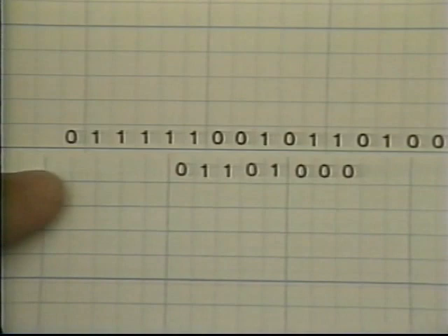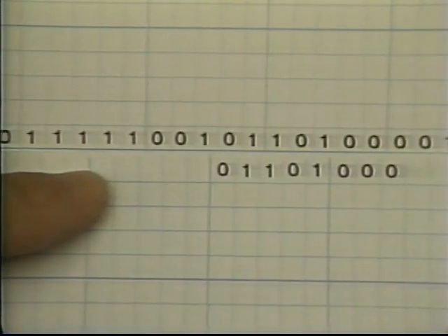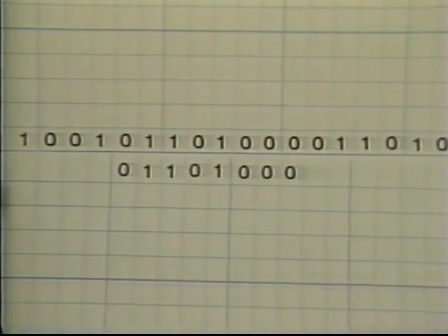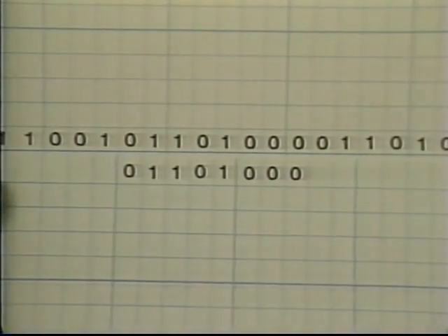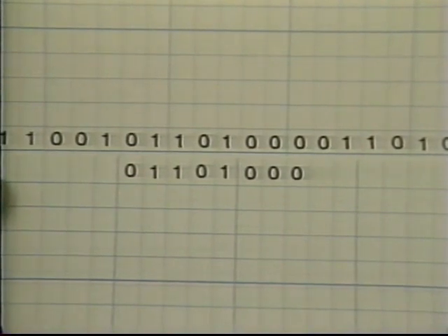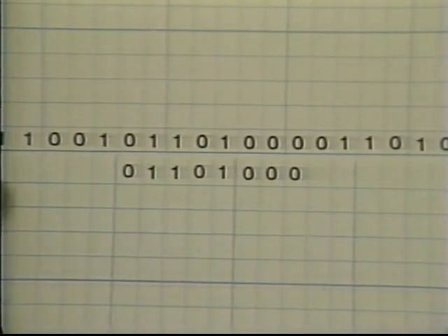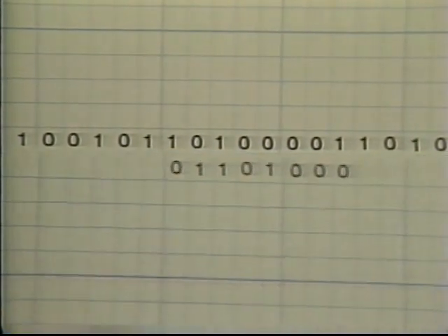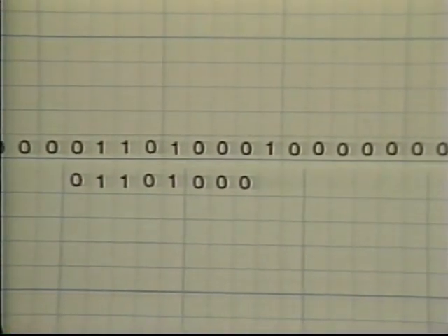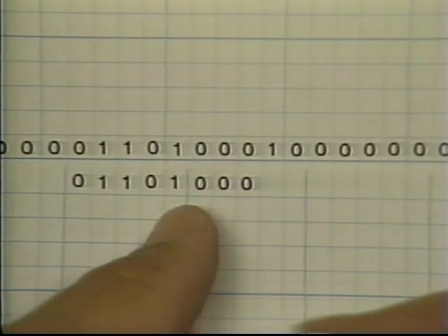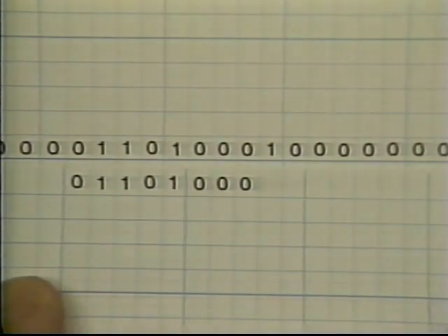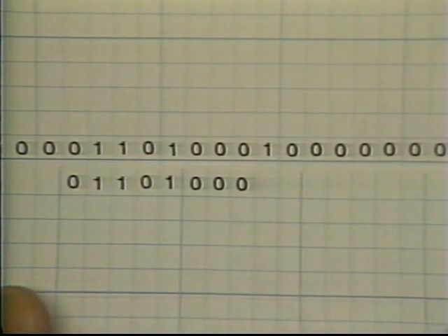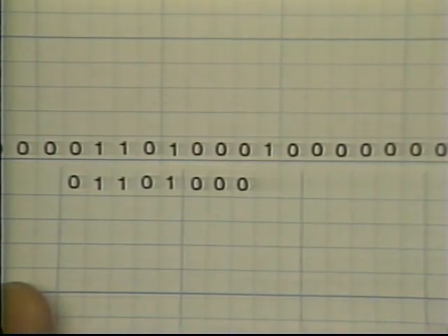As it's going along sampling the data line, eventually it will see an incoming sync character, and here we have it. Our sync character in memory matches up with the one coming down the line. At this point we know we've found what's effectively the start. But the computer then counts off 8 bit times after that and looks for a second sync character. So it must see 2 sync characters in a row. If it sees 2 in a row, it says, I have achieved synchronization. I found the start of the message. From then on in, every 8 bit times after those 2 sync characters is 1 character in the message.